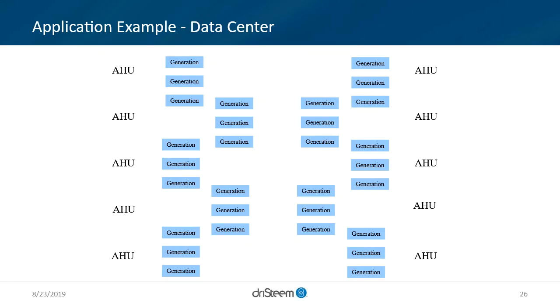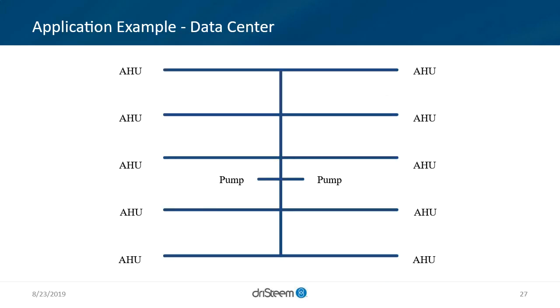So this example is a data center out of New Jersey that we supplied a high pressure atomization system, and they were comparing isothermal generators a few years back. In the specific instance for the 10 air handlers that this facility had, would require 30 generators, which can be quite costly from a capital investment. Switching that over to high pressure atomization, they were able to utilize 2 pump stations to handle those 10 different air handlers, 1 high pressure atomization dispersion per air handler.